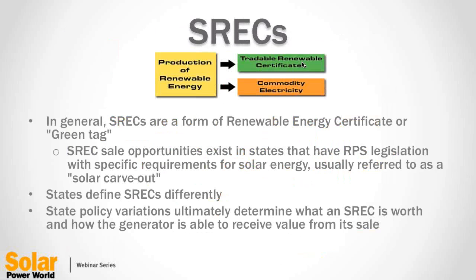And so, when we talk about solar RPSs, in a lot of ways, when we think about what it means for developers or system owners on the ground, we're talking about SRECs. An SREC stands for Solar Renewable Energy Certificate, and basically it represents proof that 1 megawatt-hour of electricity has been generated from a qualifying resource within a state. And it can be separated from the underlying electricity and then traded separately. Most states rely on RECs or SRECs to determine compliance under their standards, and as a consequence, there is a demand for SRECs from these obligated entities, and that means that an SREC has value.